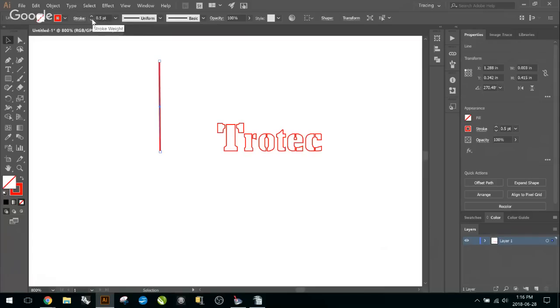Before sending it to job control, you'll want to select every line that is this thick to change them into cut lines. You can select your line, come to this button right here, select similar objects, and before clicking, click on the drop-down menu. And you can click on the stroke weight. So now every stroke weight that is 0.5 points will be selected within your new document here, and you can then go ahead and switch them over to 0.001.